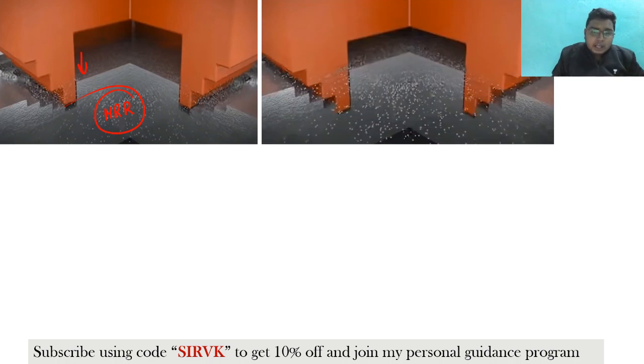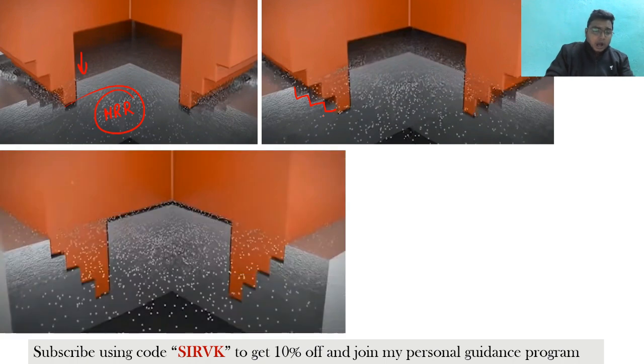Now again you are moving down, so again a very fine cavity is getting formed here. That is the same thing. That is the beauty of the electrochemical machining process, that whatever the shape features of the tool, that exact thing would be replicated on the workpiece. Again it is moving in the downward direction. Definitely we are going to get a very clear profile in the workpiece. Fine, so this is what we are going to get.